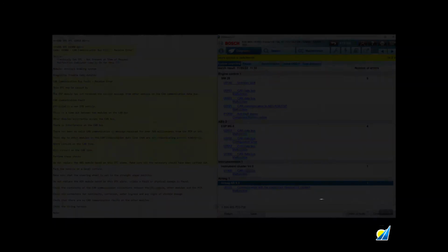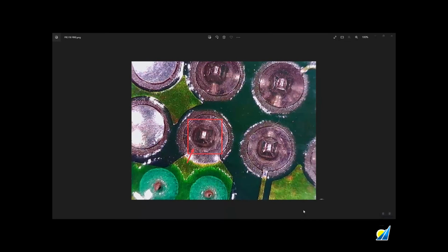So the cause of all this carnage with the CAN network was poor termination of the pins at the instrument panel. Hitting the instrument panel or the binnacle would result in a change in the CAN network resistance. If you look closely here, these are the pins that pass through from the connector on the instrument panel into the printed circuit board, and hopefully you can just see there's cracking around there. Also the pins that come through, the solder is separating there. We almost get like a cone around the pin but no contact with the pin.